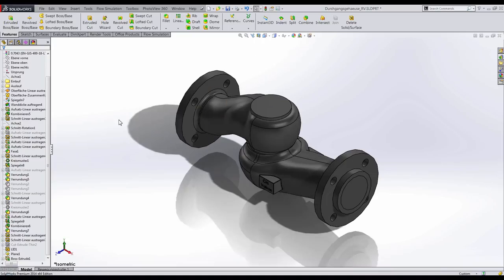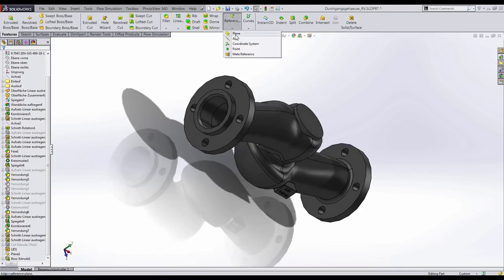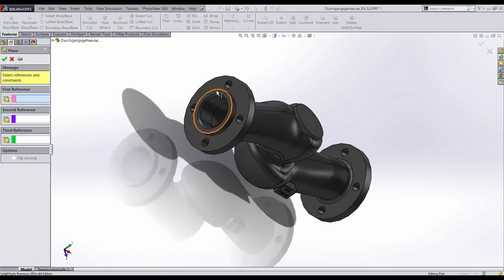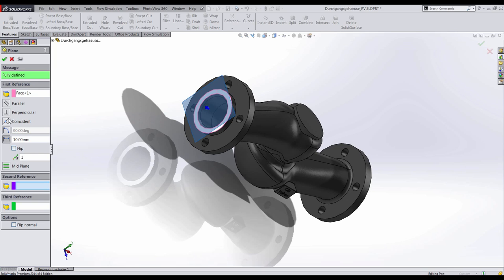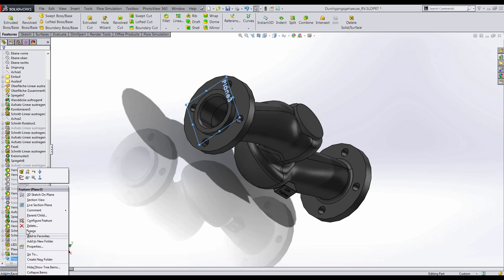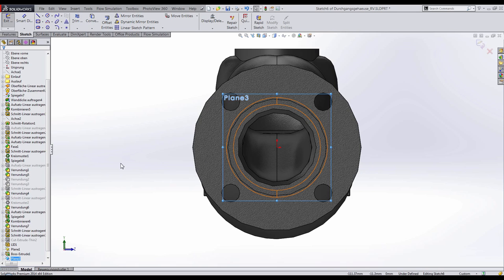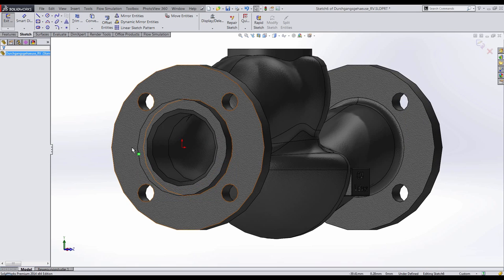Now if you don't have SOLIDWORKS Flow Simulation, you could still run a simple flow analysis using SOLIDWORKS Flow Express. Because Flow Express is a lightened version of SOLIDWORKS Flow Simulation, you do not have the option to automatically create lids, but you can use a technique of manually creating lids for all planar and non-planar faces for a Flow Express study.